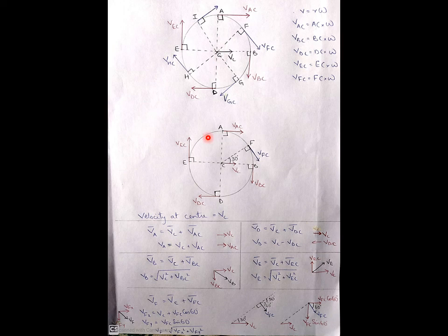What we want is the velocity at that particular point only. So again, consider the same figure. We have drawn only a few velocities over here. Consider the velocity at point C, it is VC itself. At A it is velocity of AC, velocity of BC, velocity of DC, and velocity of EC. These all things we have already said, and consider this velocity of FC also. All will be perpendicular. And assume that the CF is inclined at 30 degrees.